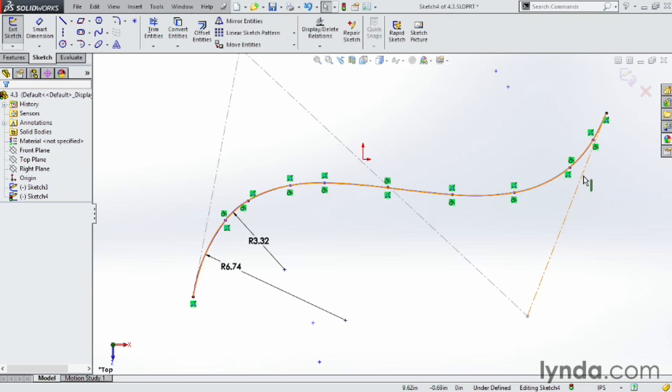Splines have many great features and are wonderful for smooth curves and complex shapes. However, use them with caution. Dimensioning, defining, and building parts designed with splines can be very complicated.